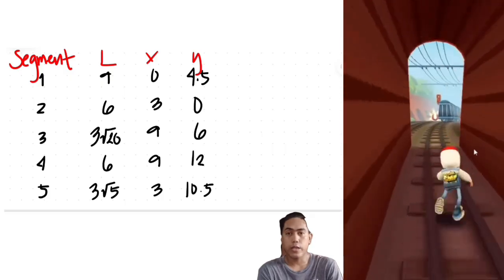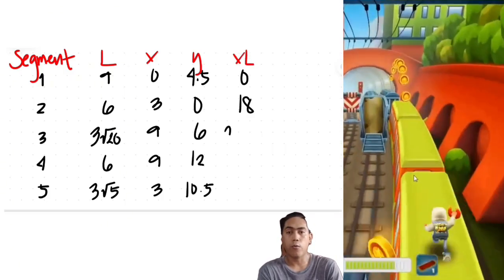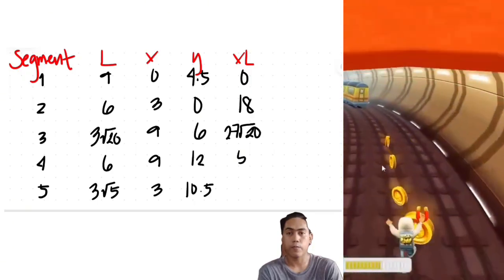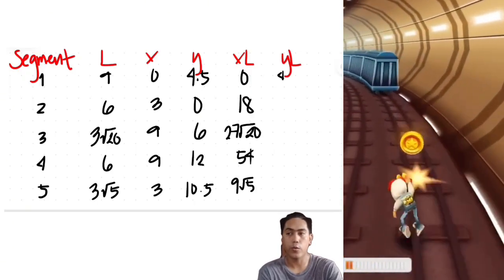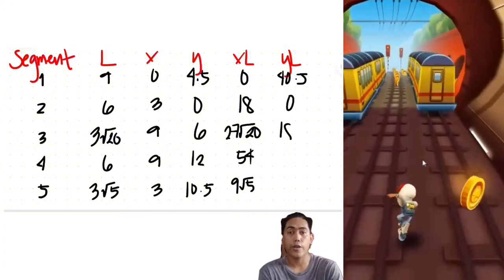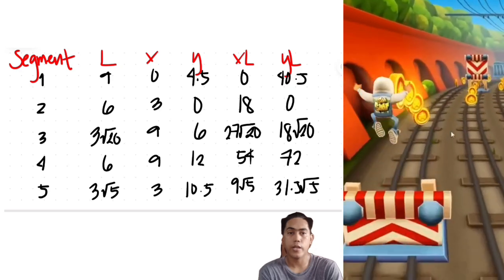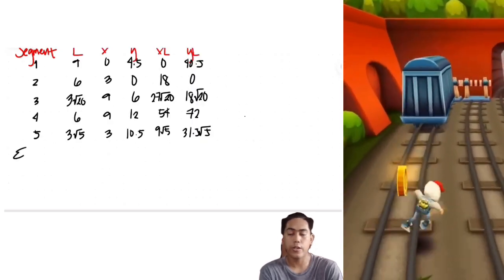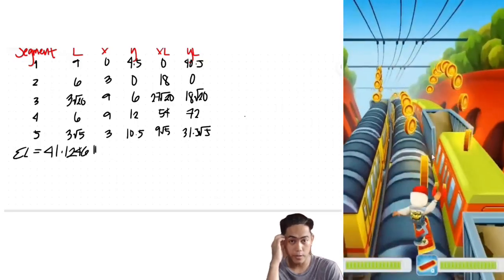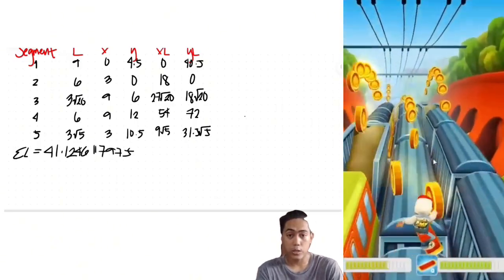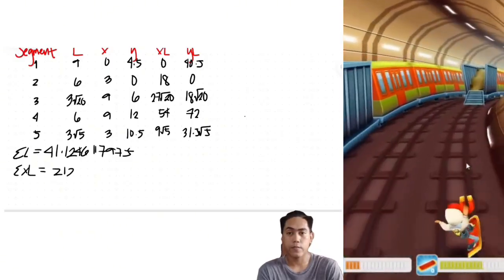The best way to solve this is to decompose the perimeter into 5 different line segments, and then solve their corresponding length, then locate their centroid, which is simply at their midpoint, and then multiply the length to the x coordinate of the centroid, and also multiply the length to the y coordinate of the centroid, and then repeat the process for the 5 different lengths.